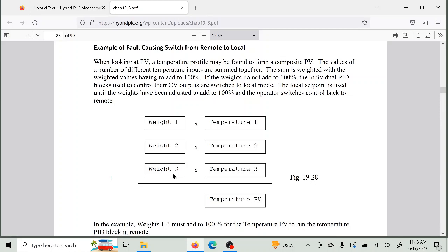Well, you have to do something. So basically what they did was they threw it back to manual. So in the program, if these 3 numbers didn't add up to 100, you put the system back in manual, and you give them an error, and tell them, hey, you got to put up 100%, or else you're in manual mode, sir. You got to get back and put these numbers to 100%.